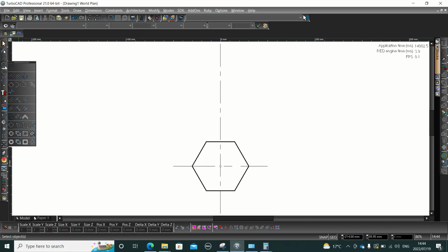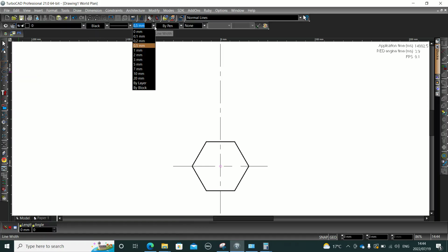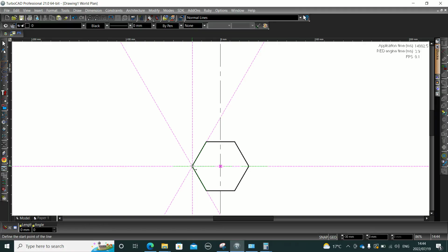Select the line tool where you took the hexagon, select line, and then change the properties to 0 because we're just doing the construction lines. Let's come here to this edge here. Once you are there, go ahead and press I on your keyboard, and then press the shift button. Just extend your line until it is high enough. I'll leave mine as high as my center line there. Look what happens when I didn't press shift.